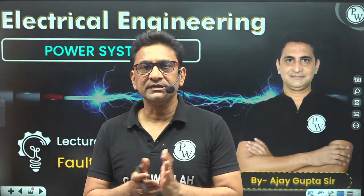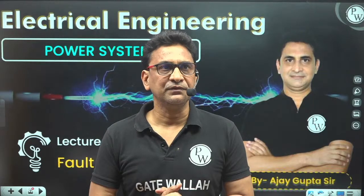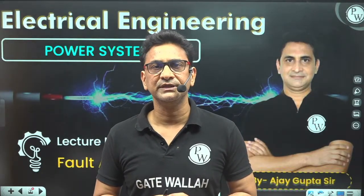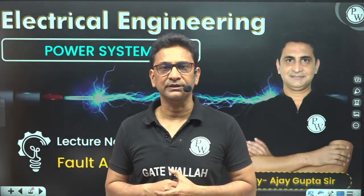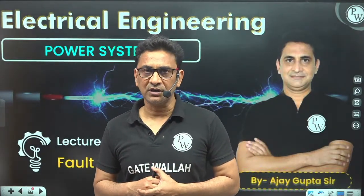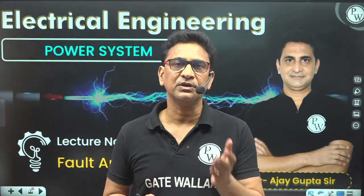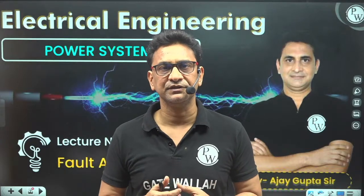Now we are discussing the line to line fault. Yesterday we started the line to line fault. Whenever two phases are short circuited, it is called a line to line fault. When a line to line fault occurs, no zero sequence current flows in the power system, only positive sequence and negative sequence current.